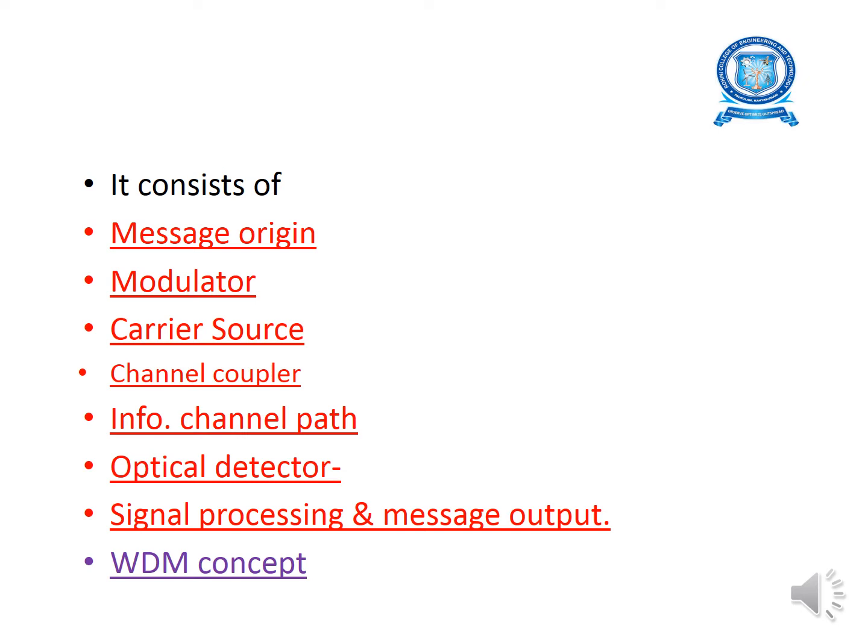The electrical input signal to the transmitter can be either in analog or digital form. The transmitting circuit converts the electrical signal into an optical signal by varying the current flow through the light source. Then the optical source, which provides the electrical to optical conversion, may be either a semiconductor laser or a light emitting diode.